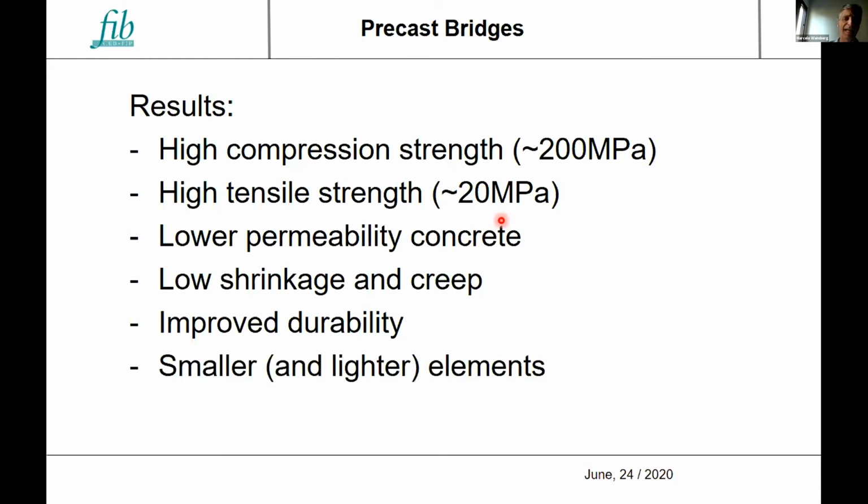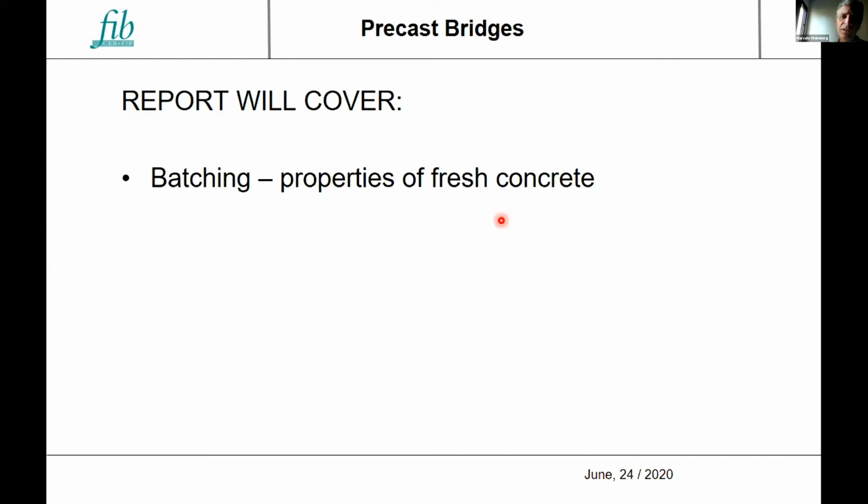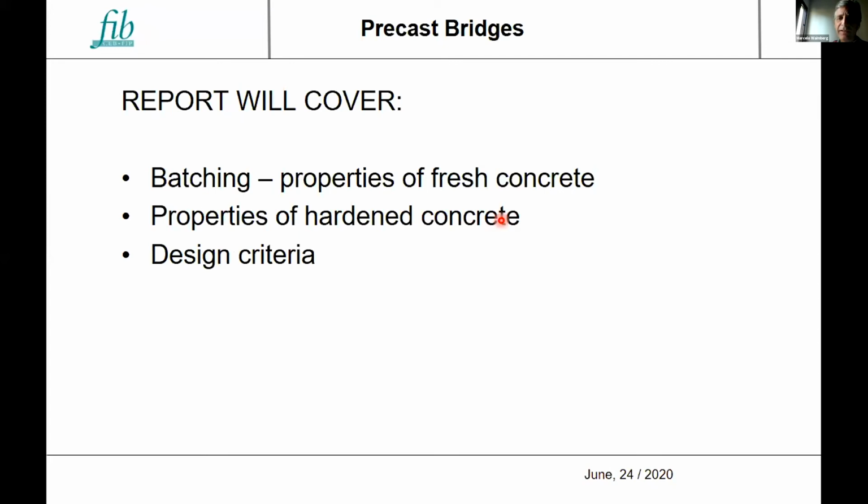You will also get smaller and much lighter elements, and the icing on the cake, very little reinforcing steel, except for pre-stressing steel. And the report will cover batching, so properties of fresh concrete. We hopefully will provide some guidance on batching this concrete. For sure, properties of the hardened material, design criteria.